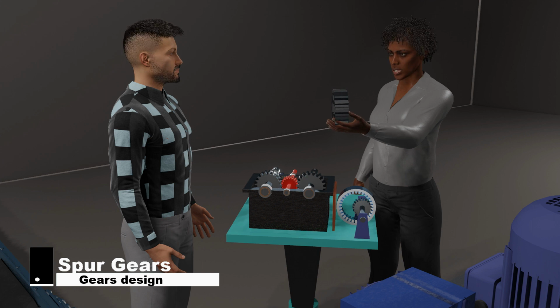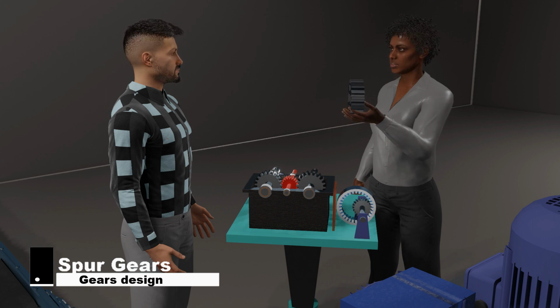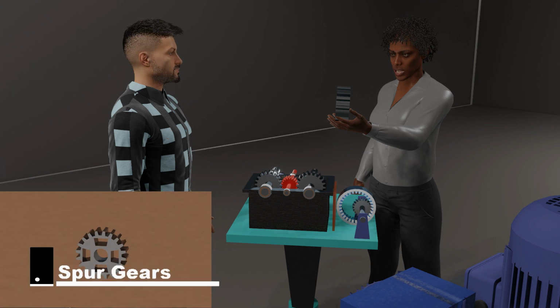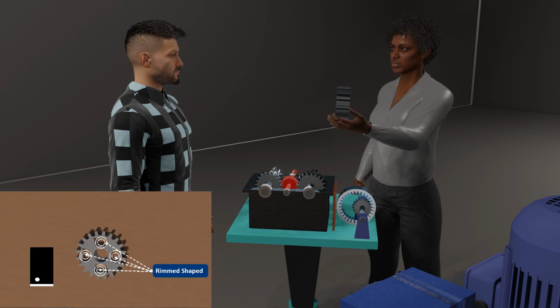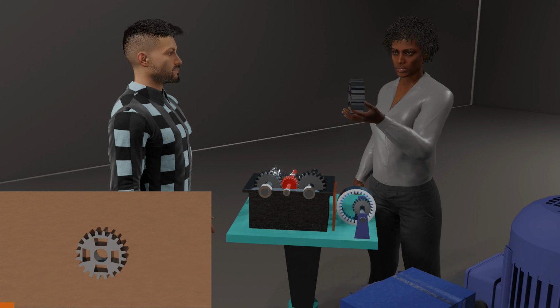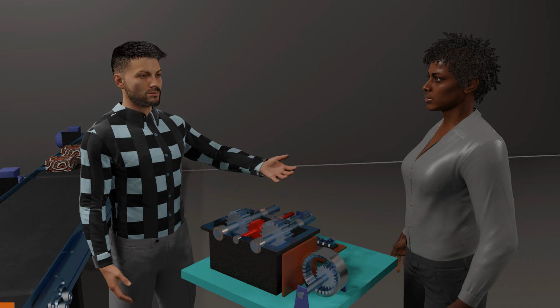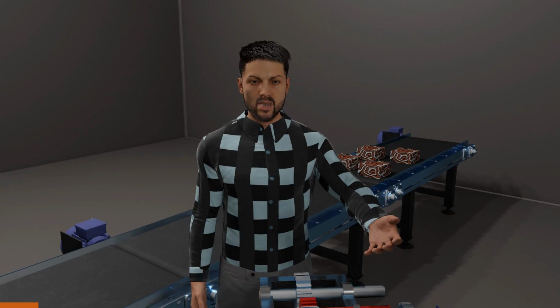Now, by design, when the diameter of the spur gear is large, this gear of larger diameter won't be made as a solid gear. Instead, it will be in the shape of a rim of different shapes as per design. With this type of metal manipulation, metal material will be saved, and the overall weight of the gear will be less when compared to gears that were not machined and shaped with a rim. Most importantly, on the gear weight, it is important that the weight of the gear is reduced to some extent via rimming.